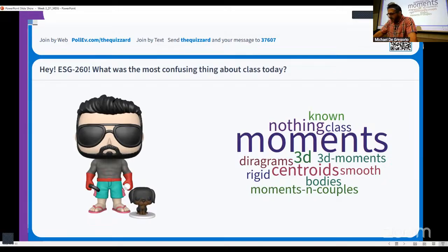We use those so often that you will just end up remembering them. They are the two most common ones. We showed in class, well, what happens if I have a trapezoidal loading? Oh, that turns out to be two triangles and a rectangle. So we just break it into pieces, right? And you're like, well, it doesn't seem like it's very engineering of you.